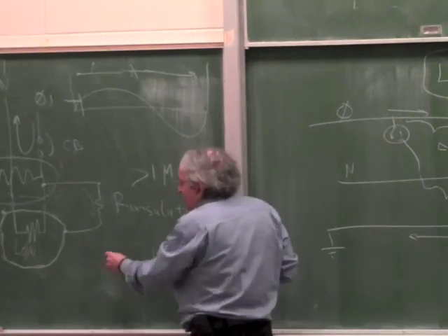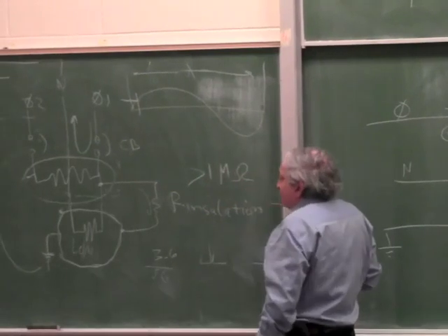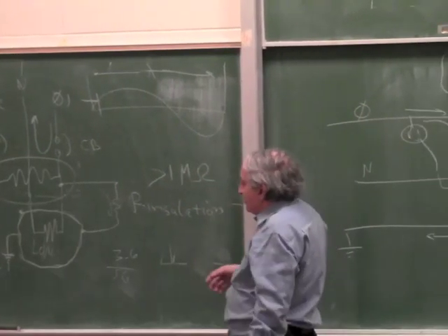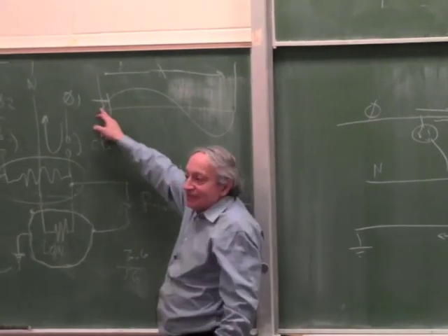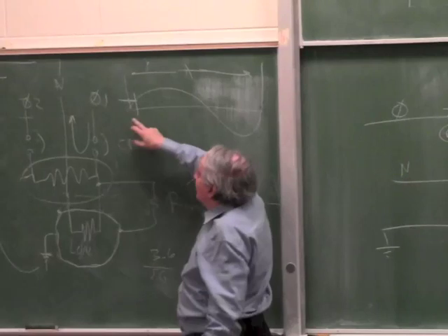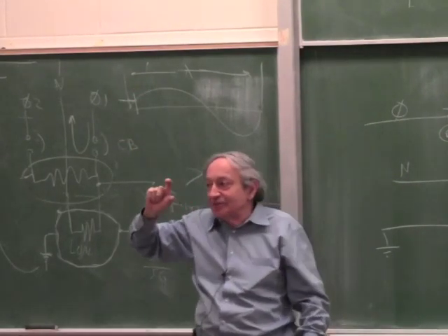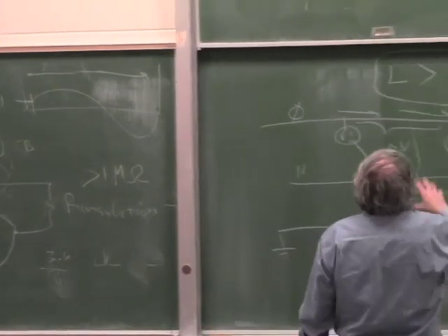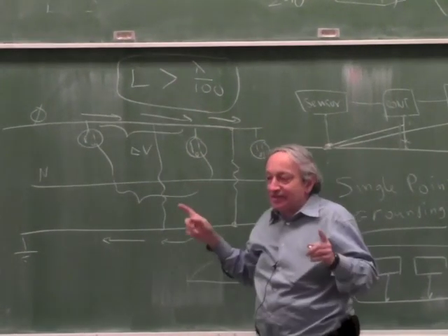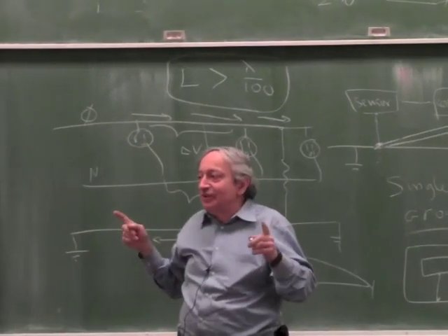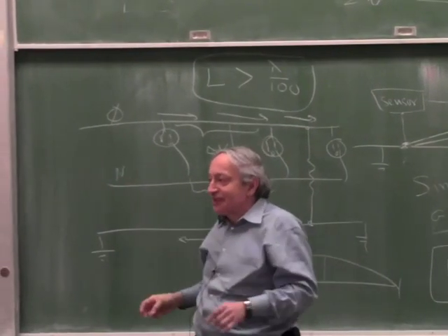Because do it in radians, 3.6 degrees divided by 57, so let's say it's a 15th of a radian, so this would be about 6%. Roughly, you can look it up on your calculator, but if this is 1% of the wavelength, this is going to be like 5-6%, so it's already significant voltage. So that's why this is kind of a good guide. If you're dealing with items or wires which are 1/100th of the wavelength or more, you have to treat it as RF. So there are different rules of design.